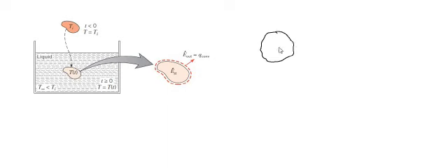Here, what we are considering is that the temperature gradient inside the steel ball is not present, which means that at every point in the ball, the temperature is Ti. Wherever you take, the temperature is Ti. So there is no change in temperature with respect to space, so there is no temperature gradient. That is the basic idea behind the lumped capacitance method.